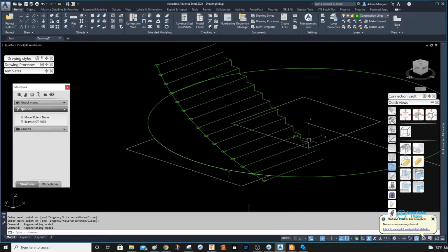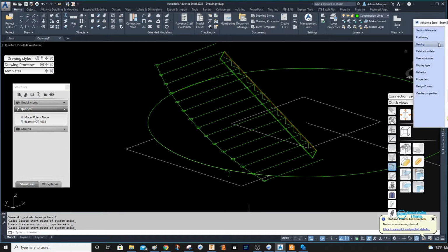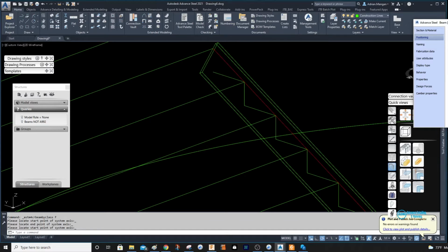Now the inside stringer can be created fairly simply with the flat bar. We can go from this point, we want to go an extra point here, we want to go 1 extra point here. Now obviously we don't want to create that on that layer, but let's call this stringer. So we'll put that in a stringer, and it's metal, and it's on the right point, and we can either move it this way, so let's see, we can move it up 2 inches using that.